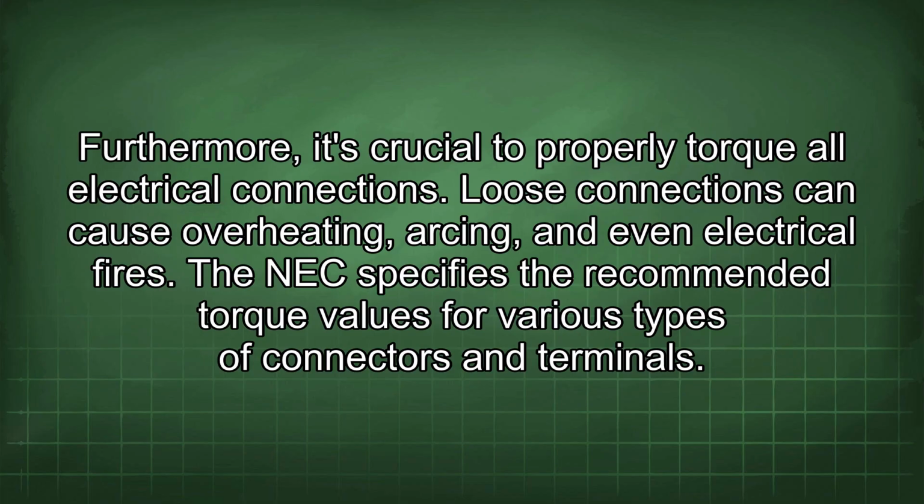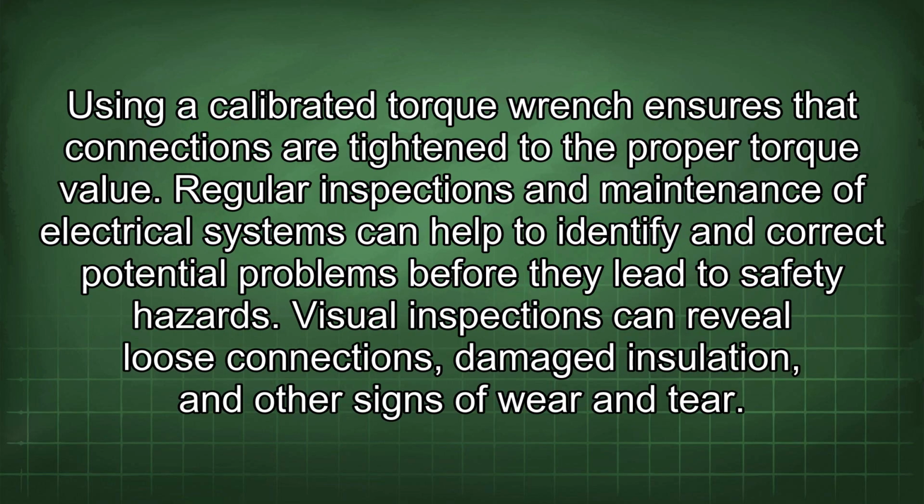Furthermore, it's crucial to properly torque all electrical connections. Loose connections can cause overheating, arcing, and even electrical fires. The NEC specifies the recommended torque values for various types of connectors and terminals. Using a calibrated torque wrench ensures that connections are tightened to the proper torque value.